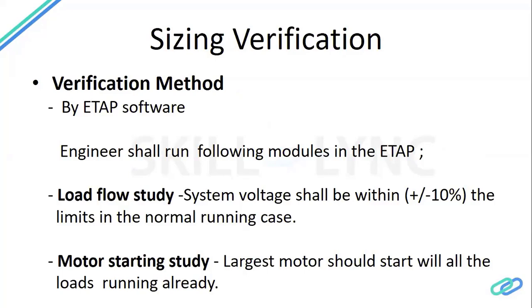ETAP is an electrical transient analysis program, which is very widely used software in the industry. So we have to run these modules in the ETAP, and I think you have heard about this study. First, the load flow study. Load flow study is used for the normal power flow in your system. Like in the normal case, the voltage and currents are within the limits.